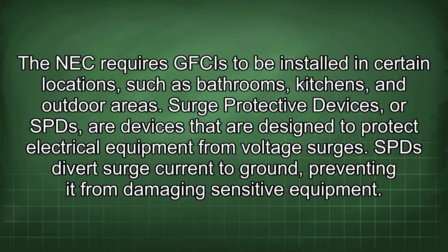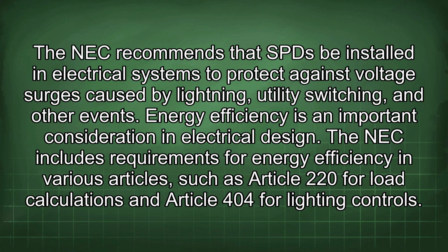Surge protective devices, or SPDs, are devices that are designed to protect electrical equipment from voltage surges. An SPD diverts surge current to ground, preventing it from damaging sensitive equipment. The NEC recommends that SPDs be installed in electrical systems to protect against voltage surges caused by lightning, utility switching, and other events.